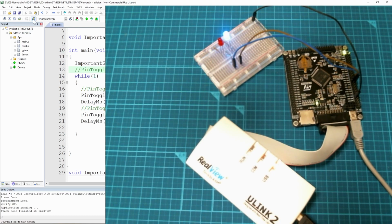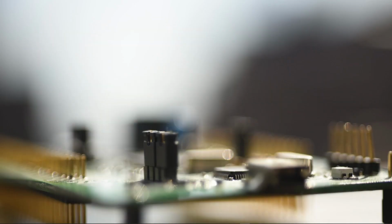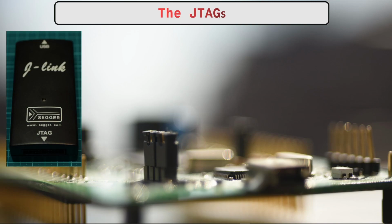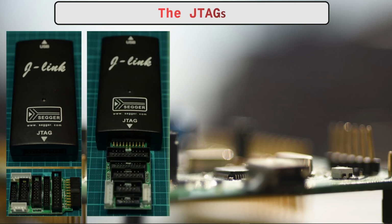So you could see this is the ULINK working well, but we still need to power the chip, and that's not always very convenient. So that's good. Let's go to our last JTAG. This is a long video, I understand, with quite some surprises even for myself. Bring back the last JTAG, which is the J-Link. This is my favorite one because you can connect it with this kind of adapter, and using this you're able to connect whatever type of connector you have. You're just limited by the cables.